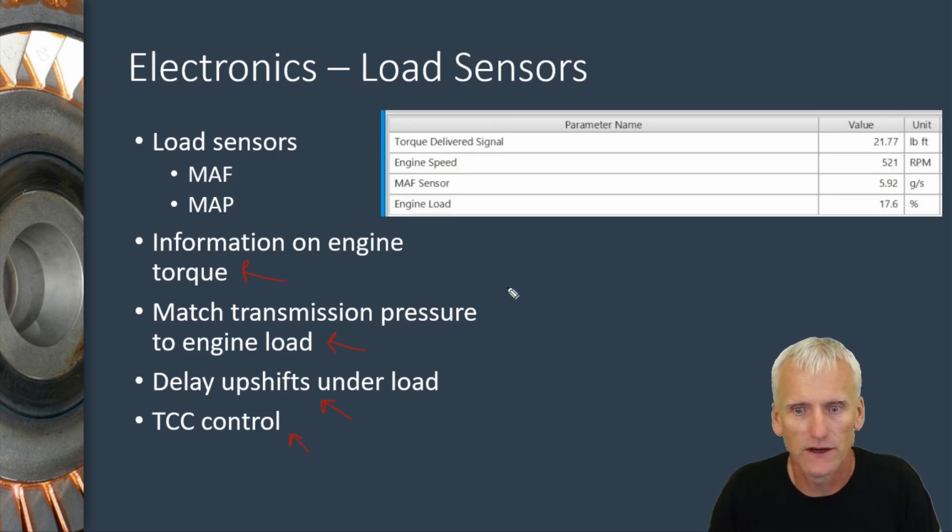So I got this video right here. I was brake torquing the Silverado. It was on jack stands, so I kind of had a hard time getting the brakes to hold. You could see they've got the actual torque value. They've done the calculation in there. It's not like they got a sensor measuring the torque. They're adapting that from the amount of air coming in. This is basically a volumetric efficiency, how well the engine's breathing.